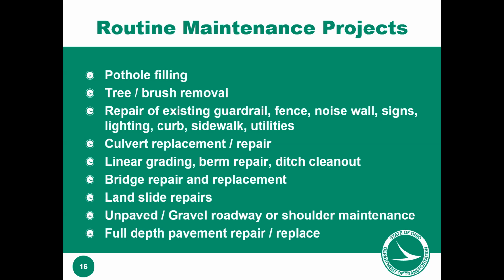So if that's kind of a safety thing, a lot of times if the hillside comes down, you have to fix it. So if you're just doing landslide repairs, you don't necessarily need an NOI. And these are for smaller projects, 5 acres or less. If you're bigger than 5 acres, you have some other considerations. Unpaved or gravel roadway or shoulder maintenance. So if you're repairing your shoulder, you can get away with not getting an NOI.